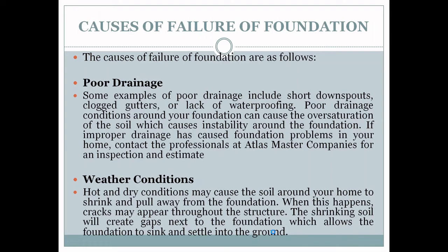Next, weather condition. Hot and dry conditions may cause the soil around your home to shrink and pull away from the foundation. When this happens, cracks may appear throughout the structure and the shrinking soil will create gaps around the foundation, which allows the foundation to sink and settle.